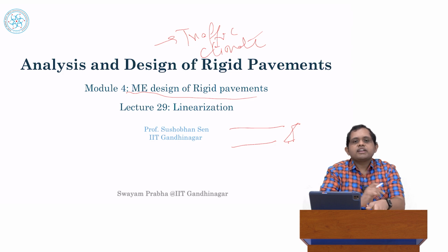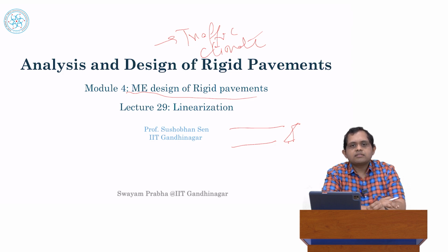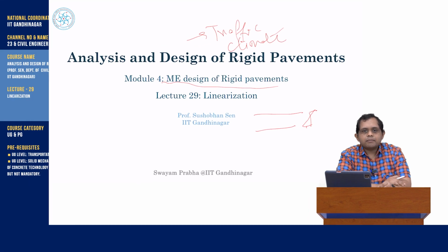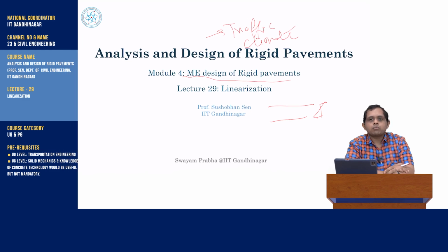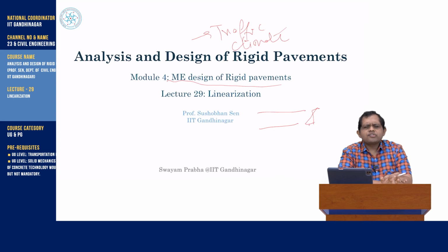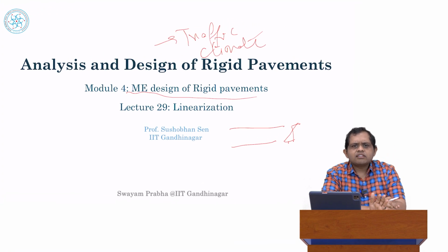So we saw in the previous lecture how AASHTO Pavement ME has a model inside it called the EICM, the Enhanced Integrated Climatic Model. And what the EICM does is it actually calculates at every hour of the analysis. It calculates the temperature profile, which will be a nonlinear profile, through the depth of the pavement for every trial design. Now, what is the typical service life or the analysis period of our design? For rigid pavements, it's 30, 40, 50 years.